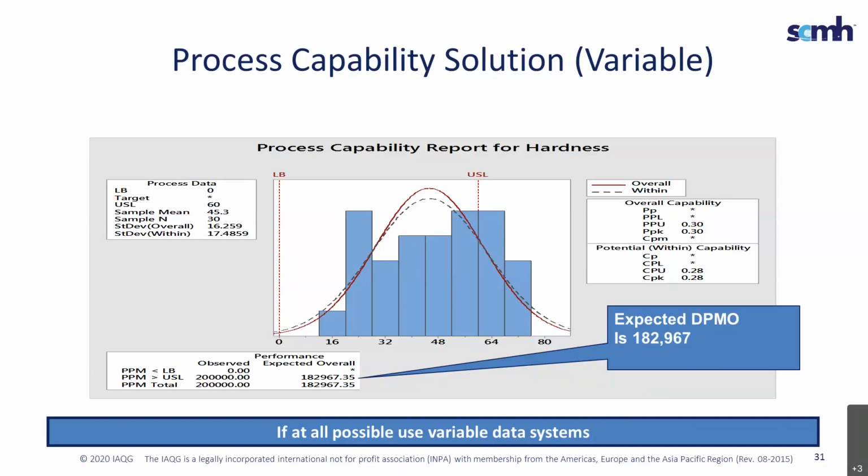Now, let's get over to those indices that we talked about before. Again, in the long term, accounting for process variation, we actually had a Cpk and a Ppk of around 0.28, 0.3. Not too different to make a huge difference. If I multiply that times 3, as I mentioned, I have about a 0.9 sigma level for this process. All right, so again, you can just calculate all of these indices and report whichever one you would like as far as process capability.